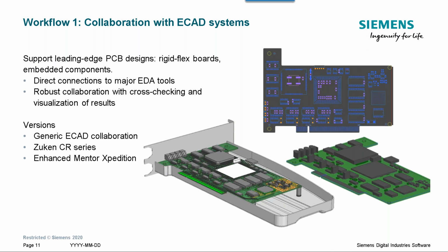So as we can see from this slide, with all the tool set in PCB Exchange, you really have the option when it comes to importing this data inside NX or Simcenter 3D to get the level of detail you're looking for. On the left, we have a detailed packaging, all the detailed 3D models for the components, and the copper with the different vias are imported as well. And on the right, you have a simplified version with an extrusion on the footprint and some filtered information. So we filtered the copper, we filtered some vias to just keep the mounting holes. So the set of tools available really allow you to import what you really need in your workflow.